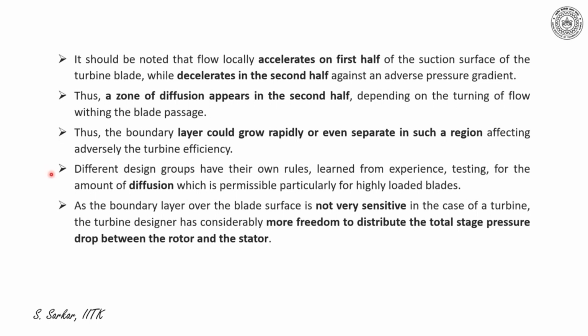Different design groups have their own rules, learned through experience and testing, for the amount of diffusion which is permissible on the suction surface, particularly for highly loaded blades.